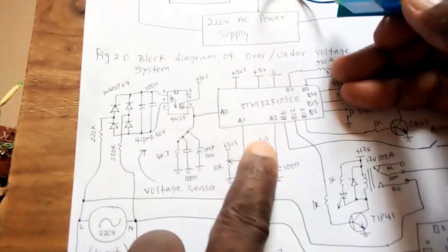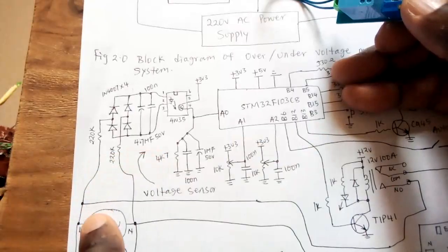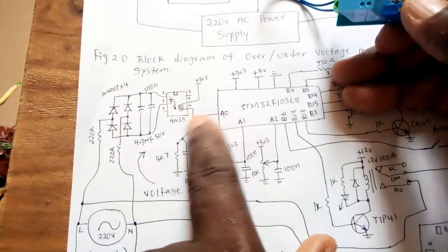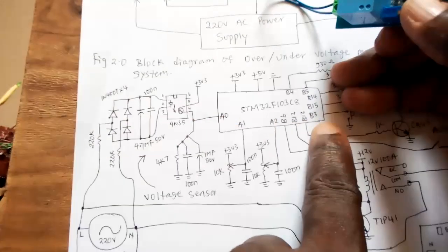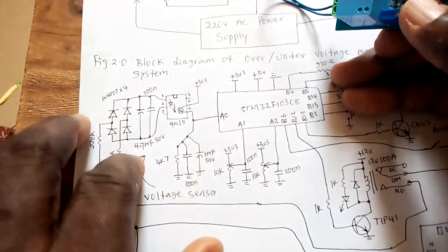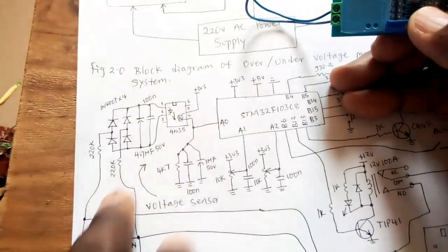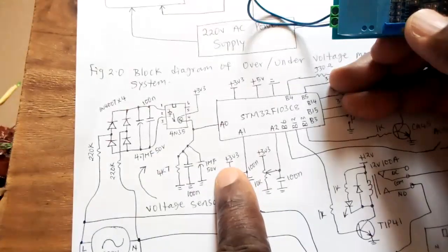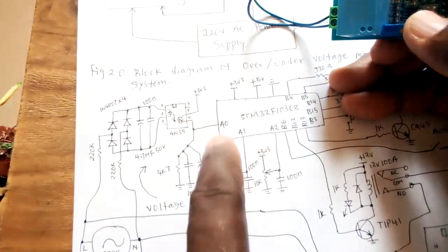So from here, I can see the values going to my serial monitor. Now, if I connect a real voltmeter here, what voltage will correspond to this value that it is reading? You can see all the values from the serial. Although I can still calibrate this to read voltages, I'm not using that because I already have my high and low reference points, which my reading is going to be compared against.